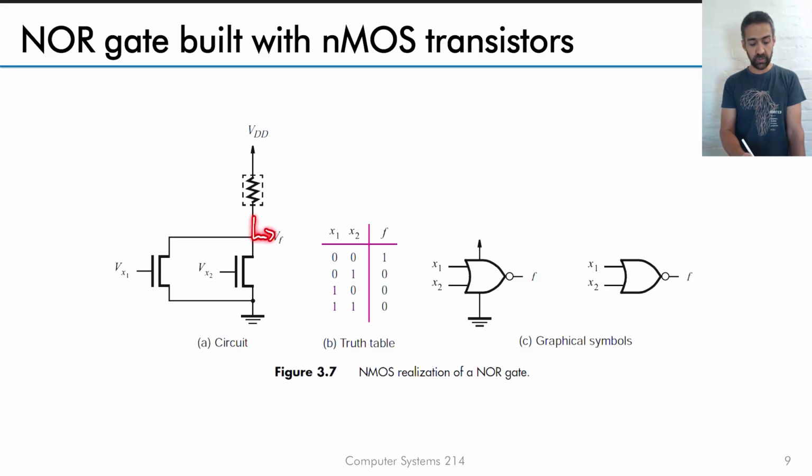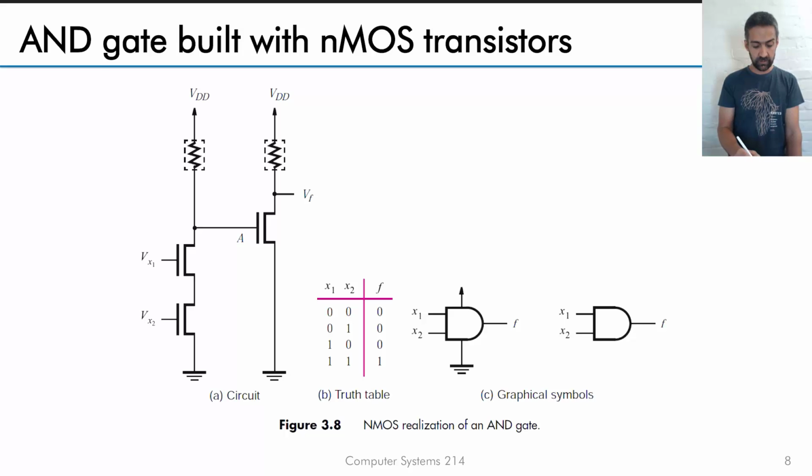Only path it should be able to find through is there, but here we have a high impedance because we don't have anything here, or if you have another device here, its input is high impedance. I'm just going to flick back, just don't lose me now. If you look at this device here, the input impedance of this transistor is really high.